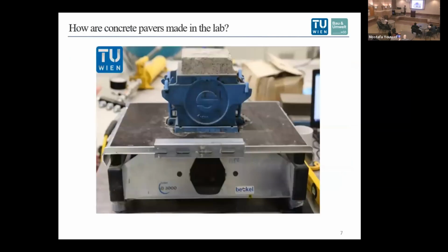So this is what we did to simulate the real manufacturing process in the lab: a vibration plate and a steel mold. You can see the screws, which were practical to demold it right after the vibration and compaction process. And for the compactor, we used this concrete sample, which was approximately 6 kilos. So not the best simulation of the hydraulic press, but the best we could do.